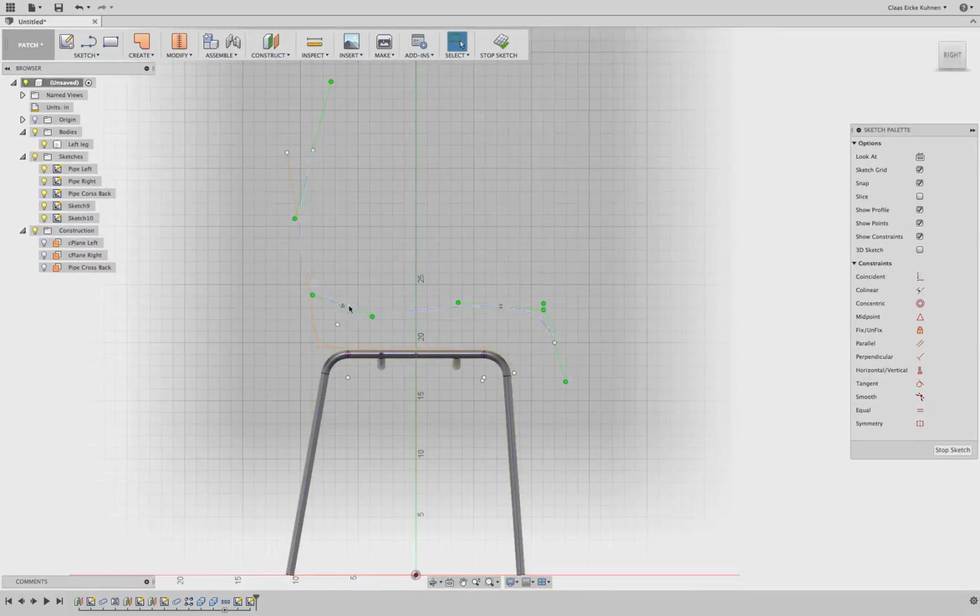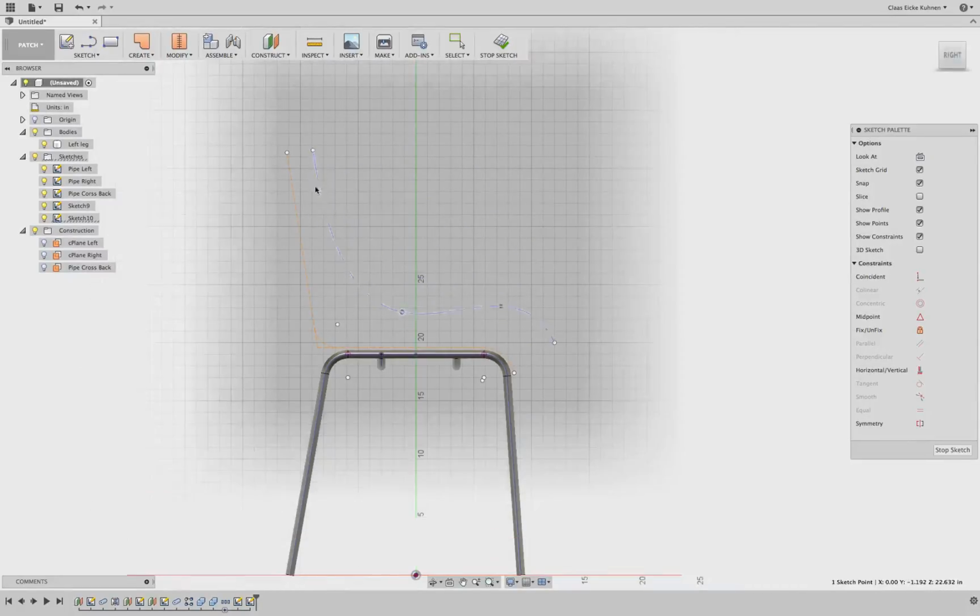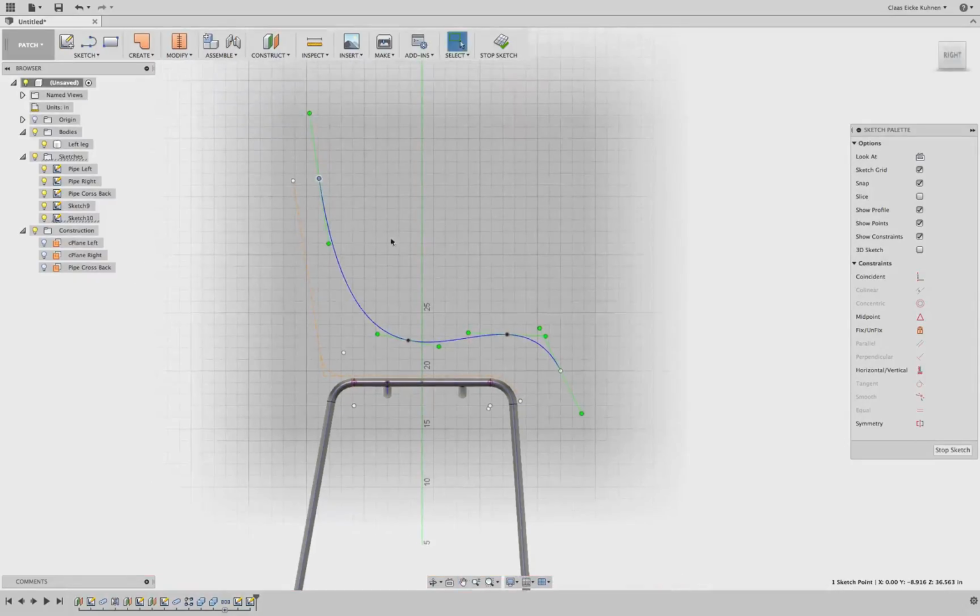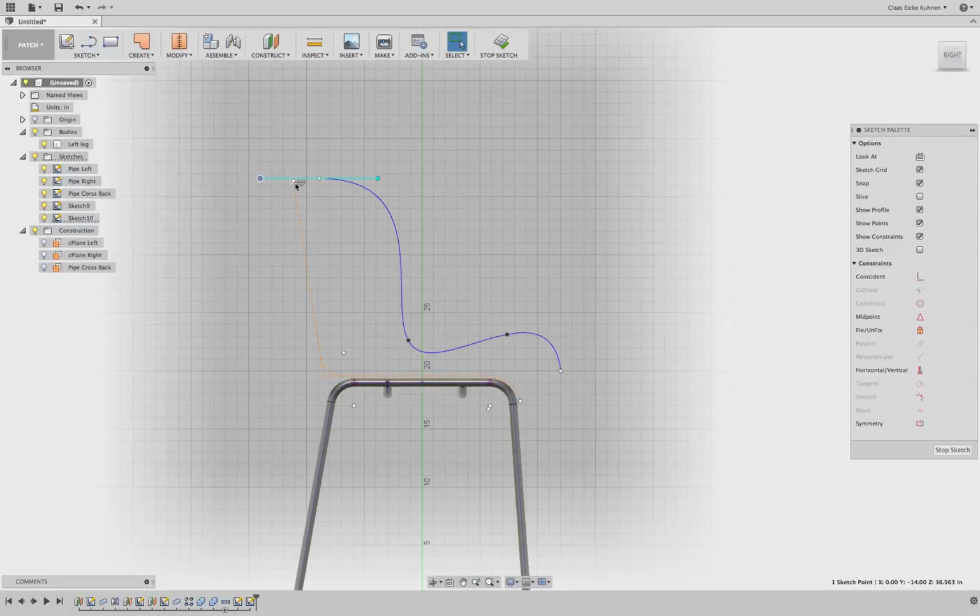And then what else do we have for spline tool? Well, we have the fit point, which we can move around, and you see based on how I adjust this fit point, the whole spline always nicely deforms. In addition, when I click on the fit point, you see there are these green handles which I can click and then drag and move around. So this way I customize even a little bit more the way how I want the spline to flow after going through a fit point, or when going through a fit point and leaving it there.